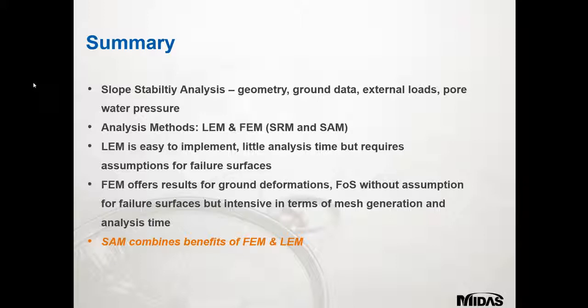The limit equilibrium method is easy to implement and has little analysis time, but it requires assumptions for the failure surfaces to calculate them. The finite element method offers results for ground deformations and the factors of safety without assumptions for failure surfaces, but is intensive in terms of mesh generation and analysis time.